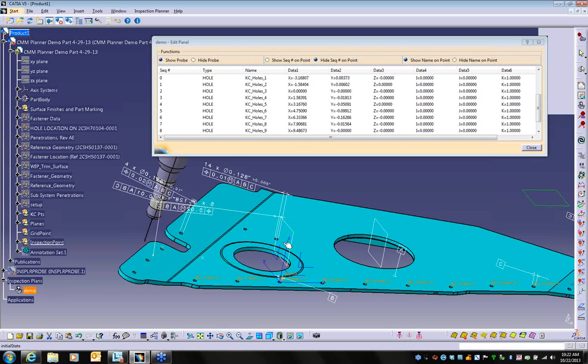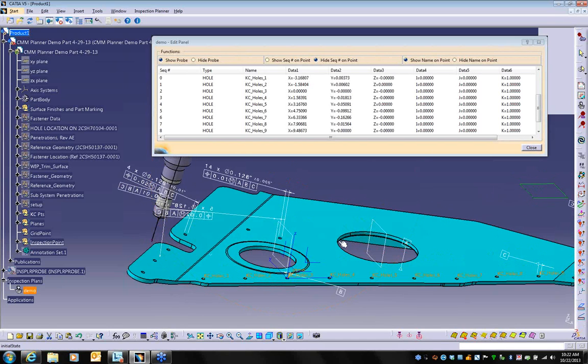Wherever we indicate, it aligns the probe to the nearest 7.5 degrees. In our settings, as probes get to be more like 1 degree or whatever, we have the ability to say what you want to round it out to. Right now it's defaulting to 7.5 degrees.